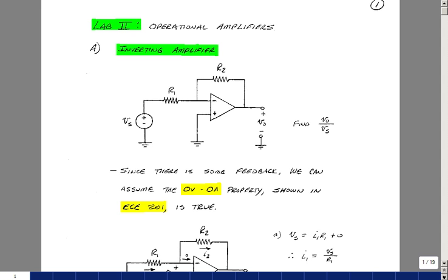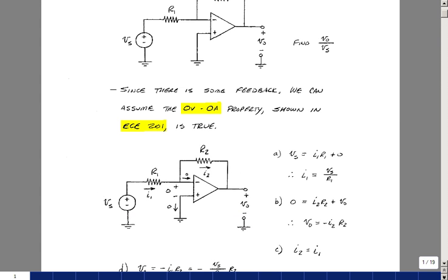One of the properties we had for ideal op-amps is that if there is feedback from the output to the input, we're going to assume that the circuit's stable, and that'll force the voltage across these terminals to shrink to 0. So we could label that on our op-amp, no voltage and no current. If we apply a voltage, most likely a current will flow. We could just pick a direction, call that I1, and maybe call this current I2.